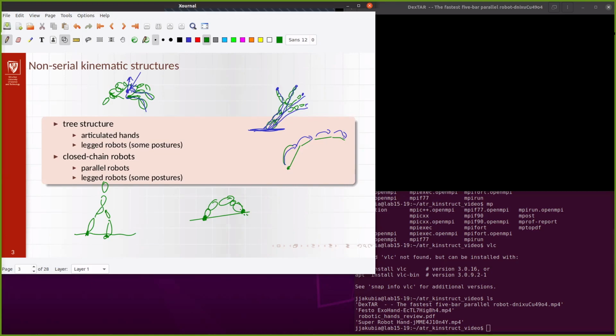So the end effector, if you treat it as a standard serial robot, starting, let's say, from here until the effector here, the effector is attached to the place and it's fixed in that point, and you have a two boundary constraint on each end to be solved. That makes some complications that maybe you know from other fields. That is, the two-point boundary problems are not so easy to solve.